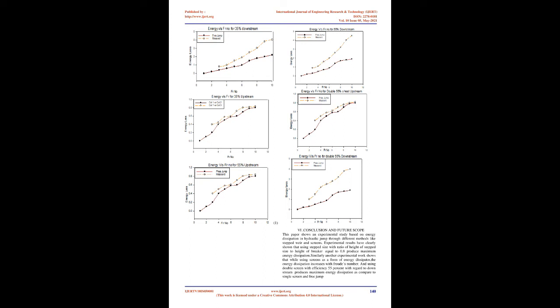Figures and table. Fig. A: Experimental setup. At the top of the weir the Froude number is in the range of 0.067 to 0.089, which proves that the flow is subcritical. Before the hydraulic jump, the Froude number is in the range of 3.02 to 3.60, which proves the flow to be supercritical and the jump in the oscillating range. After the jump, the Froude number is in the range of 0.36 to 0.42, which leads to subcritical flow with lower energy and leads to energy loss.